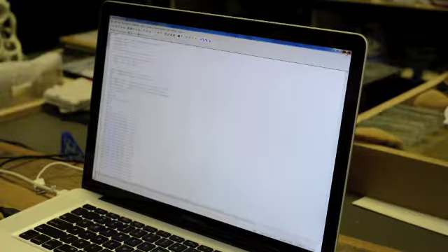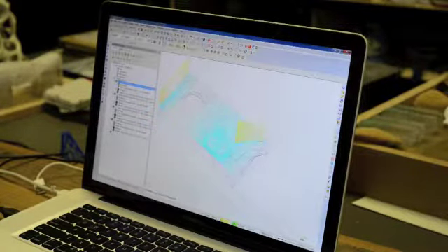So once you have the G code, save it to a USB drive. The G code is what we're actually going to put on the USB, and then downstairs at the computer, as we were showing yesterday, you're going to open up that file, the NC file, the numerical code file.